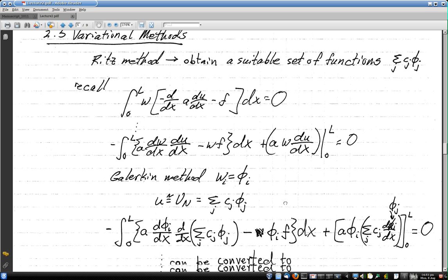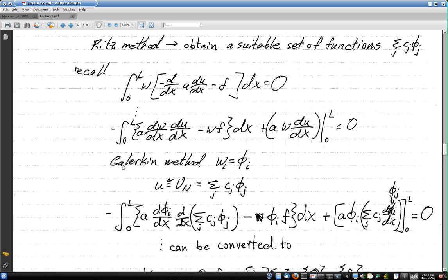And when thinking about this Ritz method, there's a specific form of it called the Galerkin method, where these weight functions, I've defined as w sub I, because its subscript notation will be clarified later, but it depends on how many finite elements you have in your system of equations.